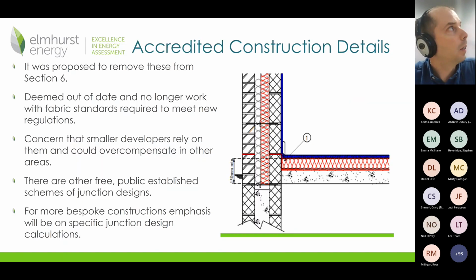For thermal bridging, the government have accredited construction details which are available, free to download and use by SAP assessors and developers. It was proposed not to remove them so much, but not update them. So they're dated 2015, based on the constructions used in section 6 2015 for compliance. Obviously, we're probably going to be building our walls, floors and roofs slightly differently now. So it was deemed that they're out of date.